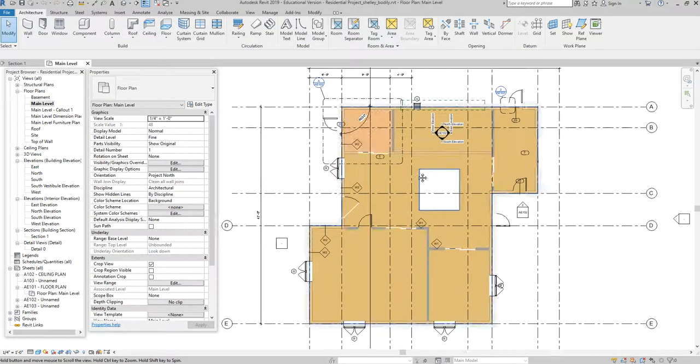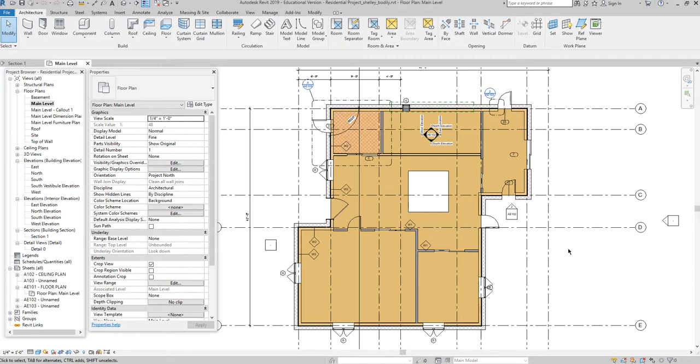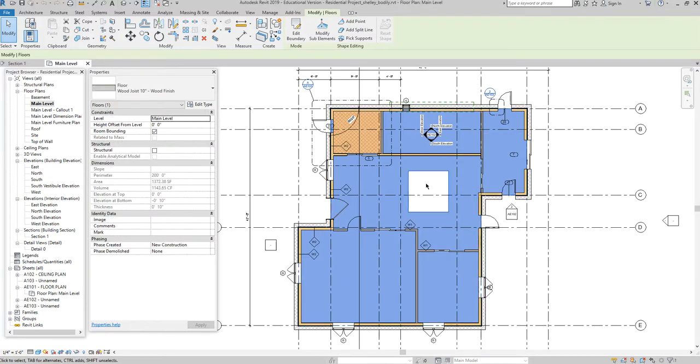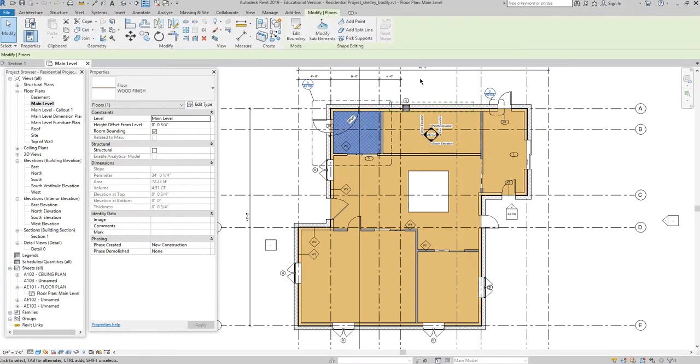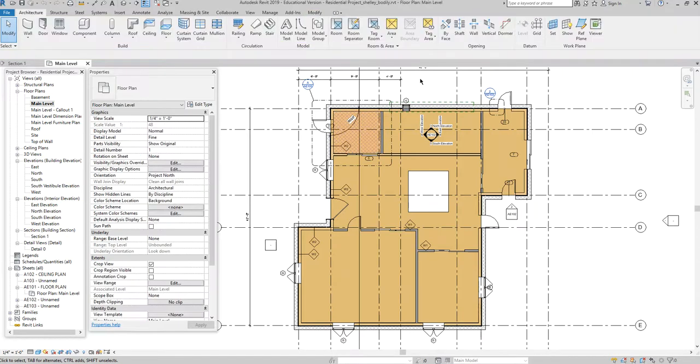One working methodology that I talked about with regards to floors was the idea that I found over the years, creating one big floor that encompasses the entire space that you're drawing, right, is a good idea. So in essence, a structural floor. And then that will have all the bare bones of structure contained within its assembly. And then having a finished floor on top of that is a good idea, right?